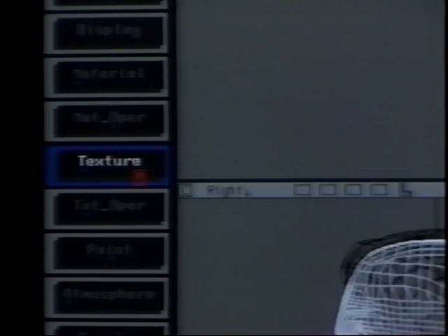Another important kind of map is a specularity map, which can determine which parts of a surface are shiny or have brighter specular highlights. We can look at this character's texture assignment, and the first map is applied to the diffuse color. Next, another map is used specifically as a specularity map. The specularity slider is up at a value of 0.7, while the diffuse and ambient sliders are both at 0. This map gets brighter in the places that should be shiniest on the character, and gets darker or black in the places where we don't want specular highlights.